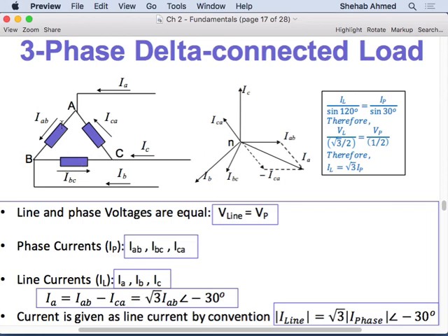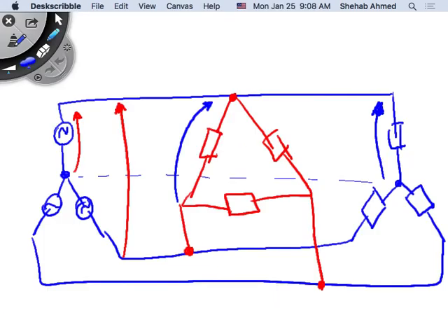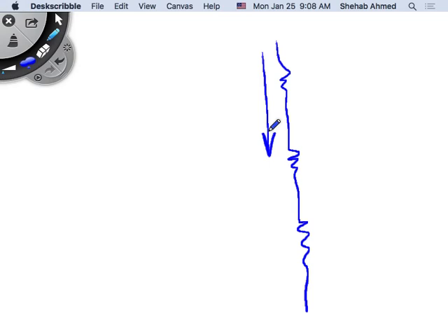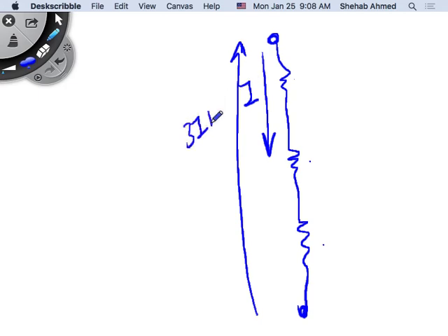No? Guys, come on. These are the 3 resistors. Currents are in the same direction. Let's draw outside. Three resistors, current is in this direction in all 3 resistors. This is I. So what is V across these 2 points? It's IR plus IR plus IR, so it's 3IR, or 3R times I. So it's a voltage that's developed across the combination.